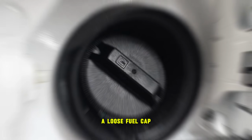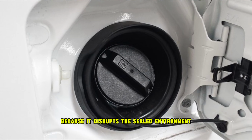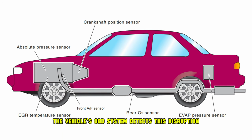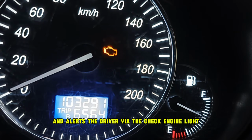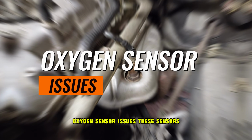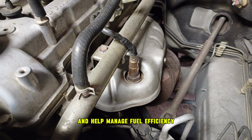A loose fuel cap can cause the check engine light to come on because it disrupts the sealed environment necessary for the EVAP system to function correctly. The vehicle's OBD system detects this disruption, records a fault code, and alerts the driver via the check engine light. Oxygen sensor issues. These sensors measure the amount of unburned oxygen in your car's exhaust system, and help manage fuel efficiency.